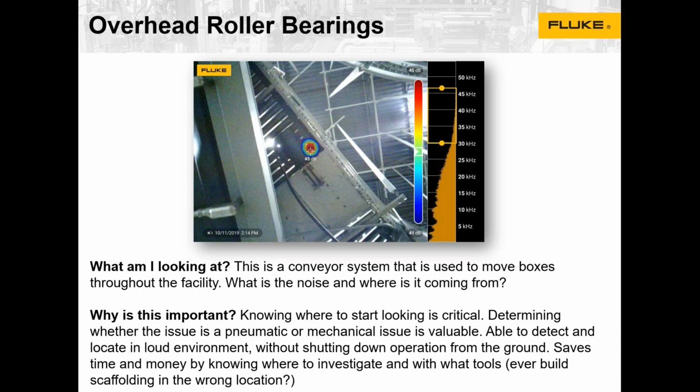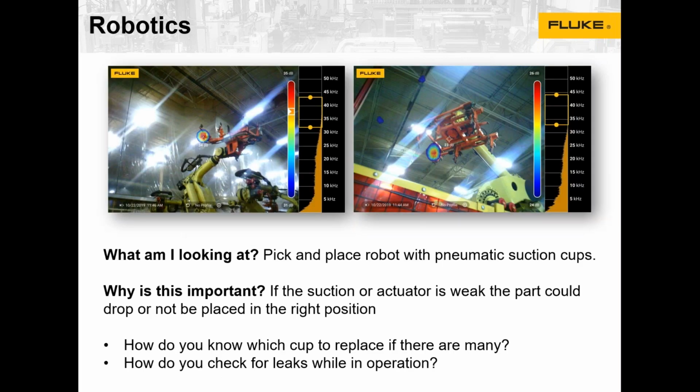And then you've got the yellow bar, which is the range of frequencies that you're visualizing sound within, isolated to that 30 to about 45 kilohertz range, where the leak is happening, or the most sound from this leak is happening, and it allows you to just eliminate all of that noise below. But yeah, that rings true here, Justin. You can see how loud it is there from the sound profile on the tool. And it's very surprising when you pick up the tool the first time that it does eliminate all that background noise.